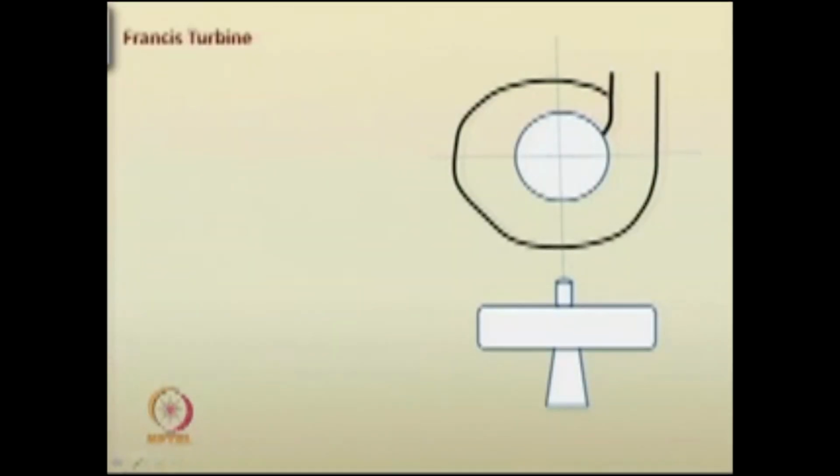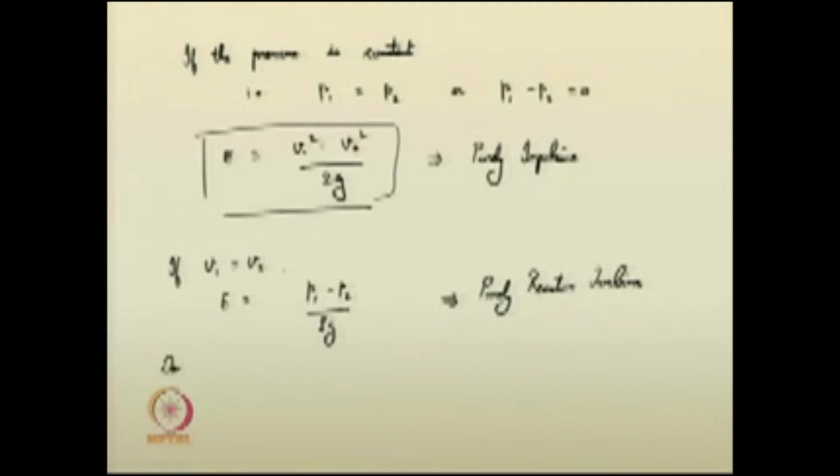Most of the turbines in practical cases will change pressure head and velocity head to a certain extent. It is not that the velocity head will be totally neglected and only the change in pressure happens; it cannot happen like that. There will be some minor changes, one may be more significant, the other less significant. Based on those phenomena, a terminology called degree of reaction can also be incorporated.